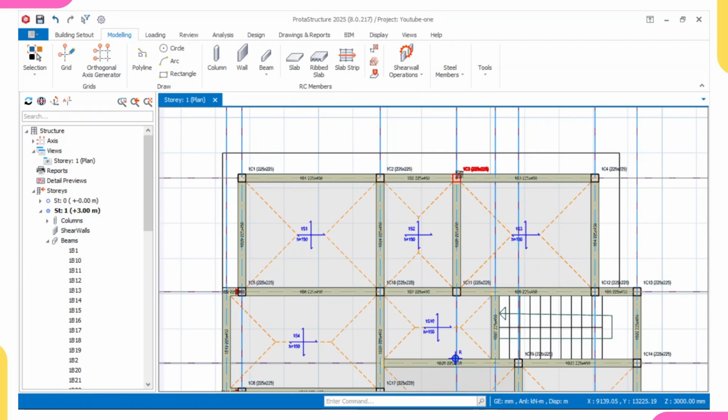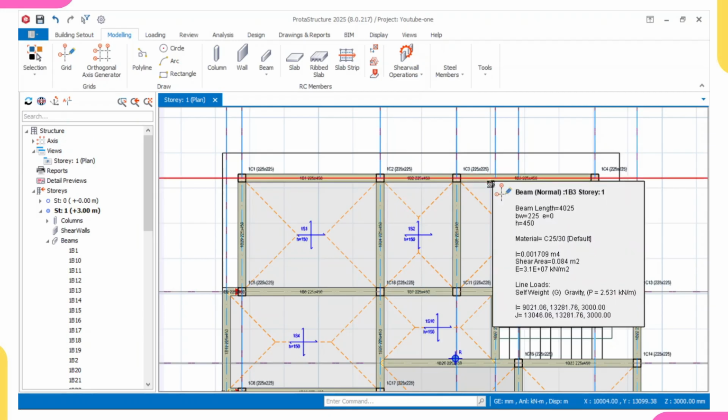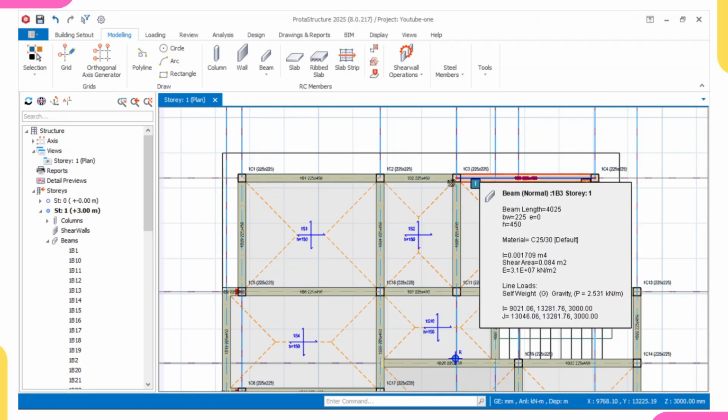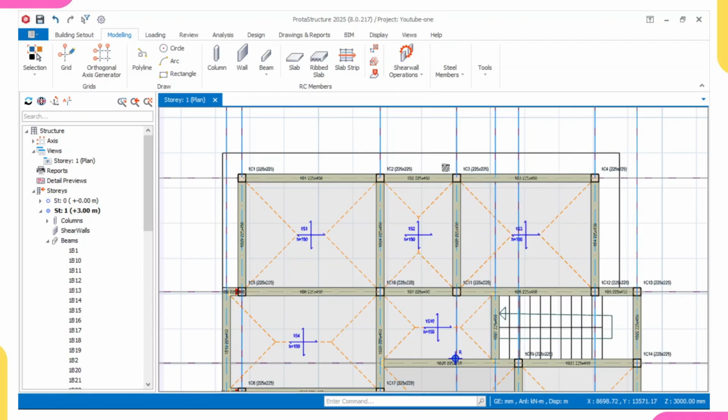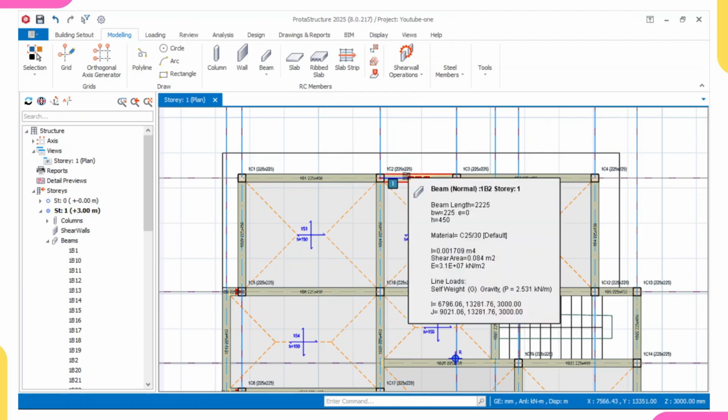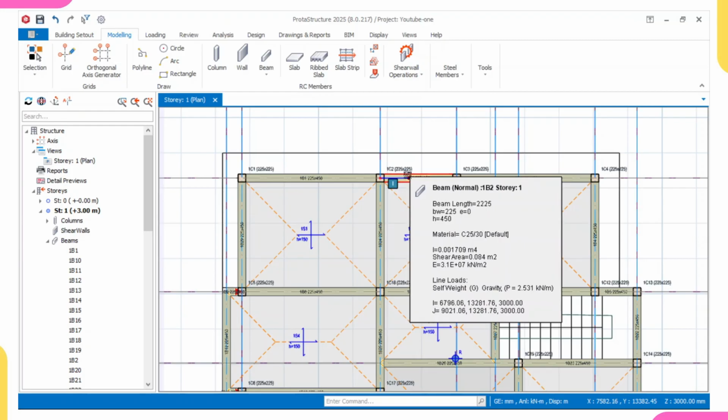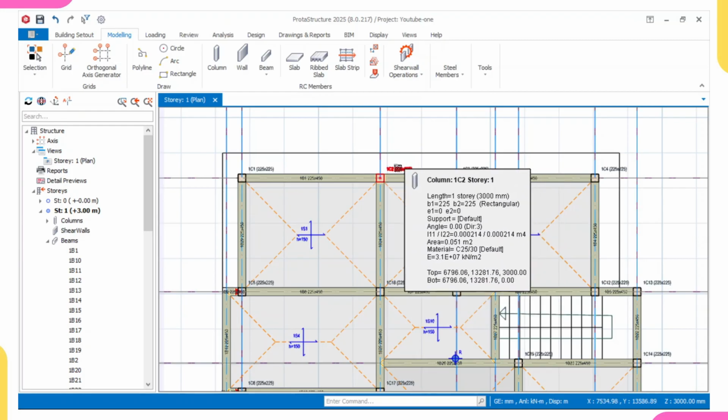So the same thing with here. There is a moment like this. That's if you can remember your structural analysis, that's in your university level. We're having a moment like this and also a moment like this. One of the moments will be positive and the other one will be negative, for example, positive 20 and negative 20. If you sum both of them, it will give you 0, because there is a rule that says that the summation of moment at any point will give you 0. I say summation, I did not say moment at any point. Moment at any point will not be 0, but the summation of the moment is equal to 0.